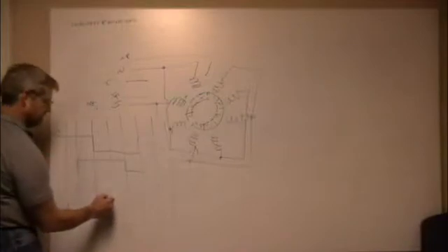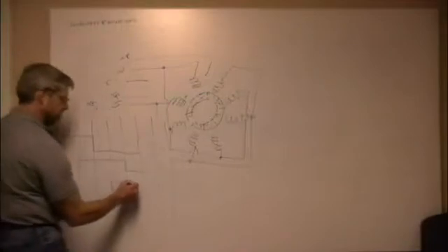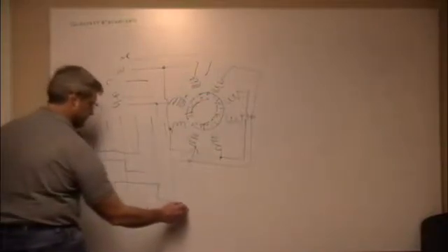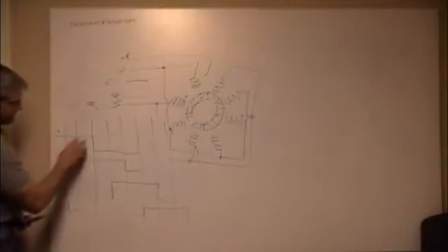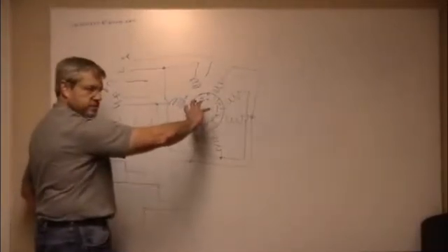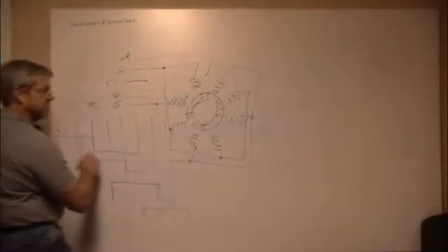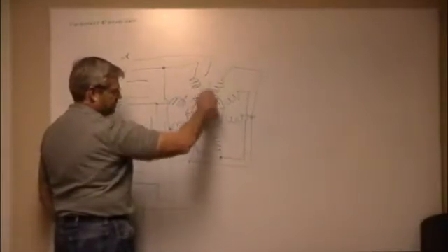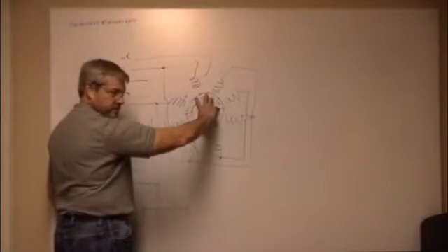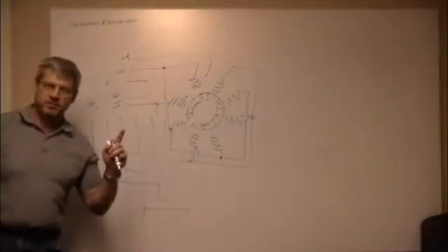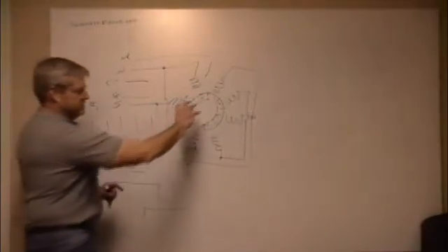Yeah, I think that's right. And then this one comes on for 3, and this one comes on for 3. So I've drawn it slightly wrong, but what happens is you get here, nothing else is on, you get that first south that gets you partway there, but then south and north are turned on, and the way it's wired, it actually moves a half step in between, because it's being pulled by this one, but it's also being pulled by that one, so it goes halfway in between.